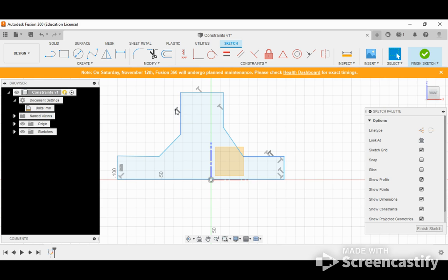Now, if you notice these are constraints that were automatically put on. And if you look at your menu bar up here, they look the most like this one, perpendicular. These are already saying this is perpendicular to that line. So if I highlight over it, you'll see that these two darkened. So for some reason, it's deciding it's going to connect these two, but it works. So these two are perpendicular. Those two are perpendicular. These two are perpendicular. So it's already got that constraint in there.